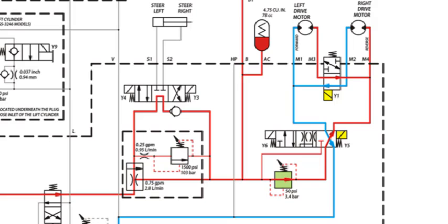The advantage of a parallel drive circuit is that there is a potential for a high pressure drop across both of the drive motors, resulting in higher torque. A parallel drive circuit effectively cuts drive speed in half, in comparison to a series circuit. The electronics further reduce the pump flow for low drive. A disadvantage to a parallel circuit appears if a tire loses traction.